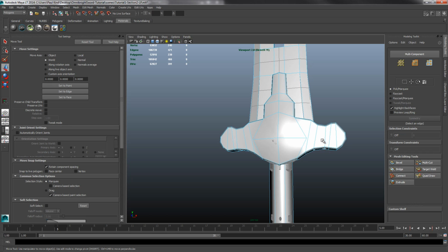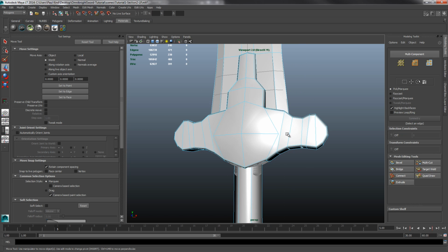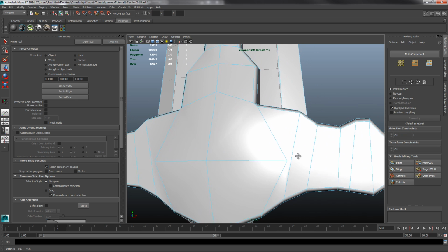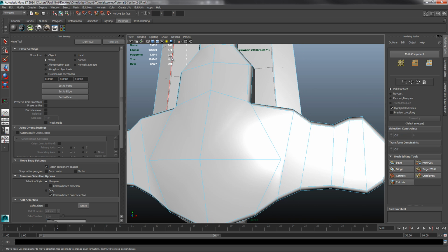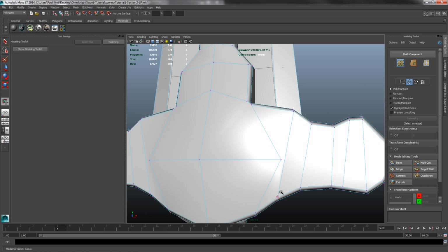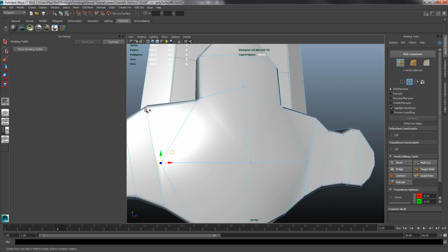Generally speaking, you can get away with more than 4-sided objects, because everything breaks down to triangles anyway. This is counting how many triangles there are. So you can get away with it, but you might want to force it. So what we'll do is go into the points, select this point and go connect, and undo the connect button. And we'll do this point and go connect, and undo the point button. So we'll do this one and go connect and undo, and this one and go connect. Oops, yeah, connect and undo.